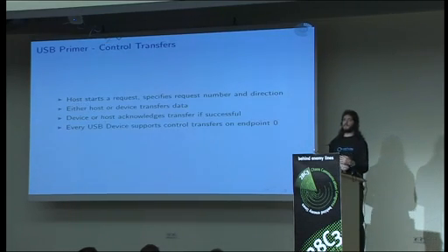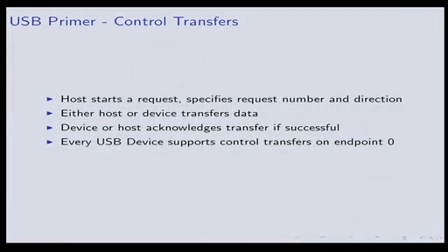Control transfers are the baseline for how USB devices talk to and from the host. It's how you get the name of the device, its configuration, vendor ID, product ID, all these things come from control transfers. And they're usually used for basic signaling information.